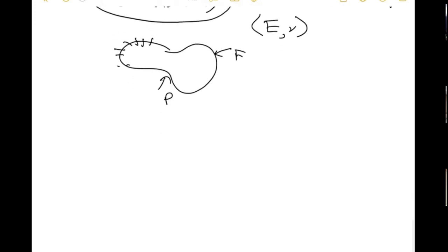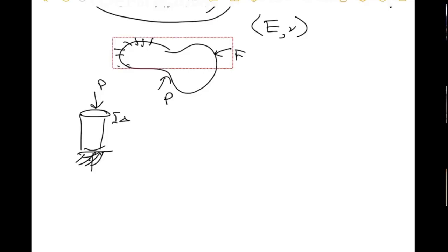There's also, though, an issue in rock mechanics. You guys tell me this. If you take a cylinder of rock, and the simplest possible test I could think of in the world of rock mechanics would be to put it between two steel plates. And typically that's fixed. You just set it on a steel plate and you apply a force P and you measure delta, right? And when you do this, you come up with axial stress.